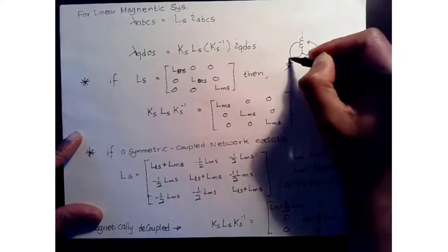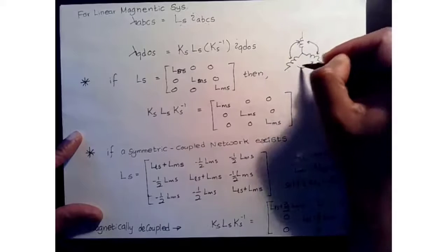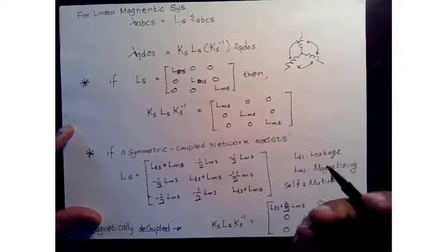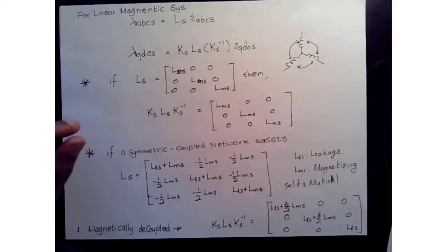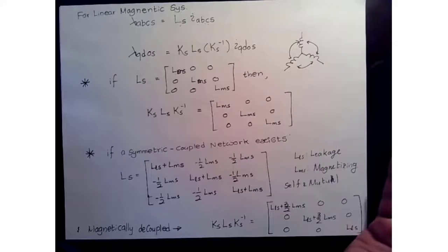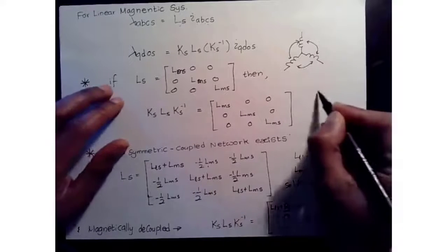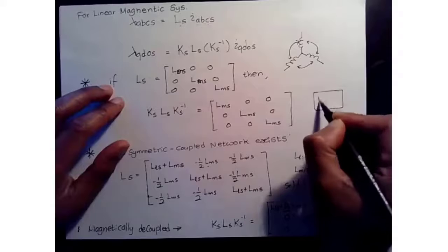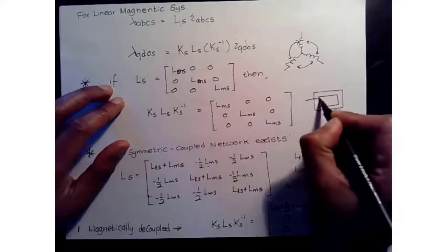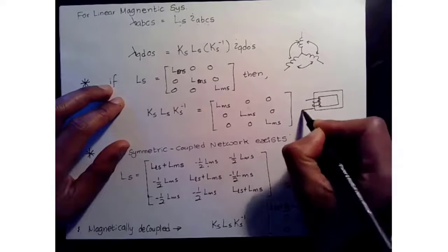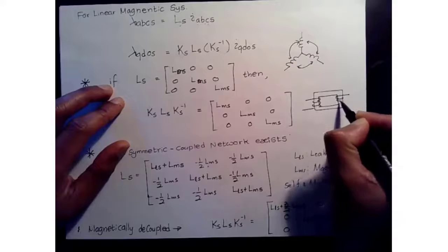Cross-coupling, okay, which means your magnetic field not only couples to itself, but it couples to other windings, other phases, which is captured through this mutual flux. Remember when we talked about transformers, the transformers that transform voltage, not that transform into vehicles.